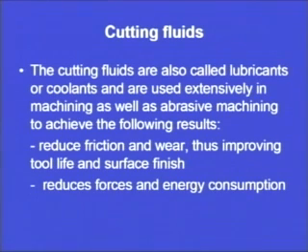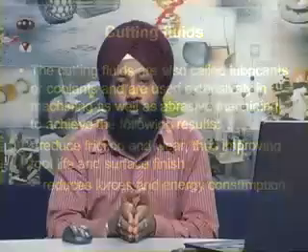Now, coming on to the cutting fluids, we have seen that there are different types of cutting tool materials available, and depending upon the requirement, we have to choose which particular material we are going to use. Now, coming on to another important aspect, that is the cutting fluids. Cutting fluids are also called lubricants or coolants. So, basically we have seen the cutting fluid has two different functions. One is that it will act as a coolant, and the other is that it will act as a lubricant. Now, this cooling and lubrication mechanism will differ depending upon the composition of the cutting fluid that we have chosen